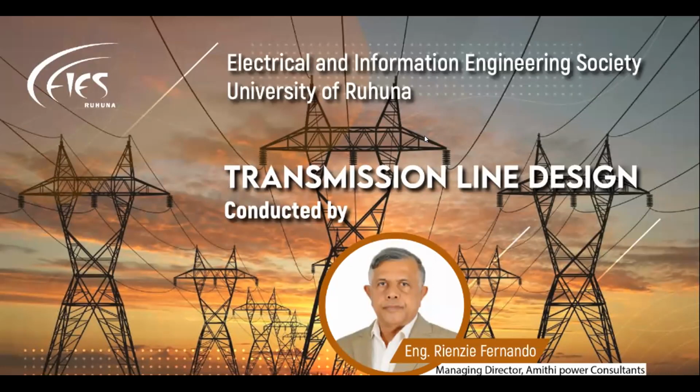It is the most difficult question I have ever faced, but I know the answer. After flashing over once or twice, the insulator is no more left on the transmission line, because it may flash over again and again, so it is changed.